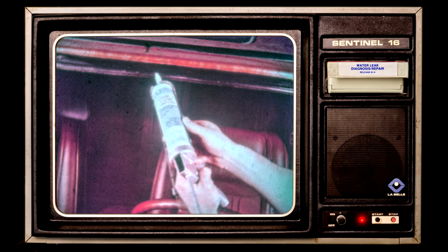Before the sealant is applied, the leak areas must be cleaned with 3M General Purpose Adhesive Cleaner or Kent Aerosol. If any water is present at the leak areas, it should be blown dry. Now we need to consult the chart for the correct sealant. We can apply the sealant between the weather strip and the windshield, then reinstall the molding. Again, any excess sealant should be removed.